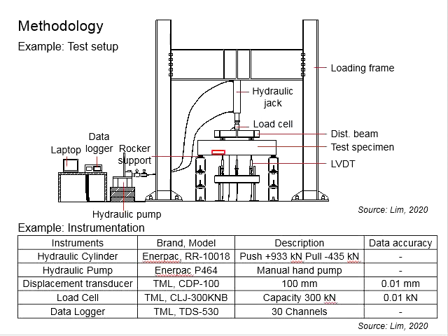And then you have 3 displacement transducers here, 1 at the midspan, 2 just below the point load acting onto the beam. The measurement here cannot measure the deflection of the beam. It actually measures the vertical displacement or vertical movement of the beam at that particular point.